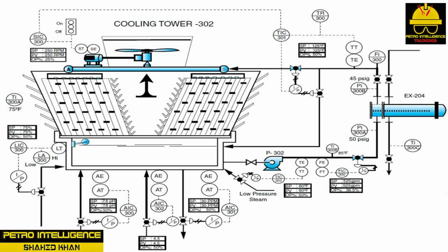The fill provides a vastly expanded surface area interface that enhances air-liquid contact. As evaporation occurs, the air becomes saturated with water and is carried out of the cooling tower system. CTW302 uses a fan to draw air into and across the fill. The fan is located on the top of the cooling tower and slowly draws air into the system and rapidly discharges it at the exit point. The cooled water continues to drop through and over the fill until it enters the basin.